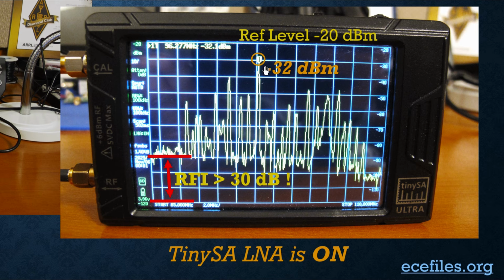And also keep an eye on this one. This is the really strong station, and if we have too much gain in our amplifier, this thing could just go up close to 0 dBm or something. It could be really bad. So the desired station is about, let's see, minus 85 dBm, and this guy is about minus 30. It says minus 32, but due to the resolution bandwidth here and the signal moving around, it's probably about minus 30. So minus 85 and minus 30.